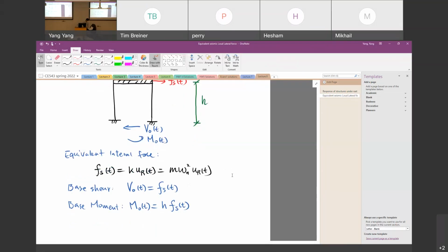So when you do structural analysis, if we can calculate the displacement of the mass, we should be able to tell the reaction force in the foundation, as well as show the shear and moment diagrams of the columns. That is very important for our design.